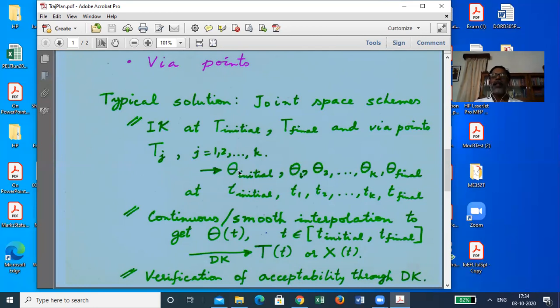Now, planning a continuous motion from here to here is nothing. It's very easy. It's an interpolation, and you will get a continuous function. Planning from here to here is also straightforward, equally simple. Another continuous motion. The point is to ensure continuity across this, then across this, then across the next, and so on. And at initial and final, whatever position, velocity, acceleration is demanded. So ensuring continuity across points is the big issue.